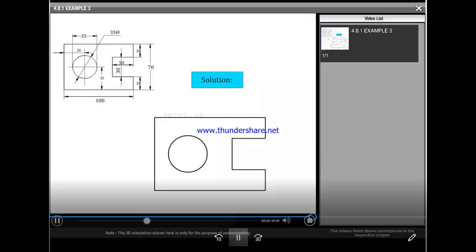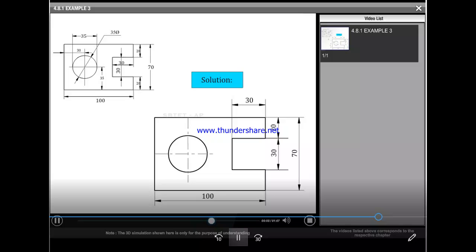All the dimensions are to be shown externally. Represent the dimensions in an aligned manner. Now identify what wrongs are available in the given figure. Now after redrawing, keep the symbol for diameter prior to the numerical value.